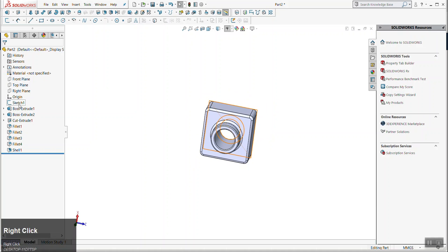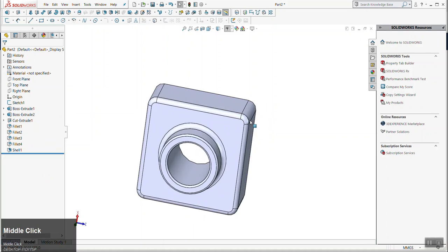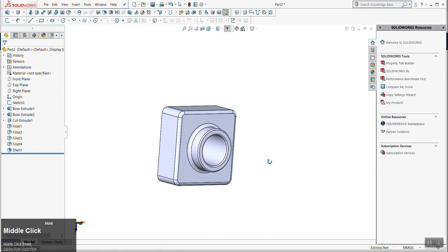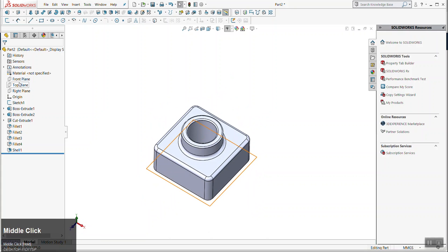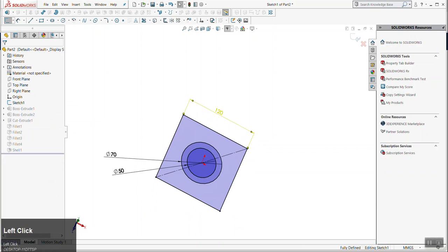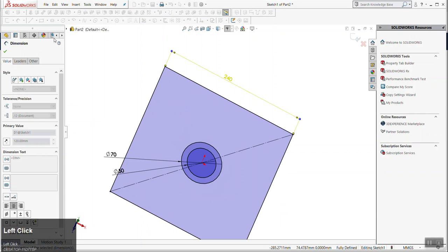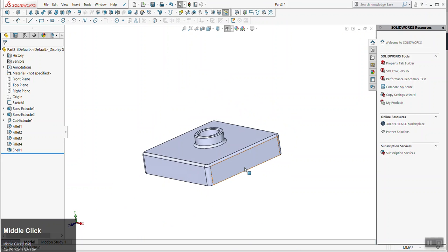But yeah, so to just illustrate that, right? It's like your boss comes over. It's like, hey, what even do we think this is? It's like a block. It's like, hey, this giant Lego block thing actually needs to be bigger. You can then go to your master sketch, edit it, and it's like, all right, how big do you want it to be? You want it to be twice as big? So let's make it 240. Click that checkbox, exit out of the sketch, and then it rebuilds.